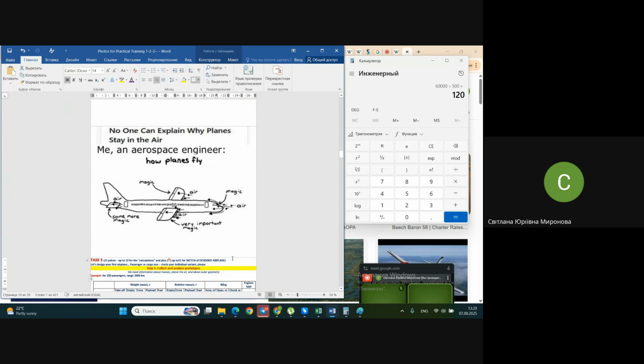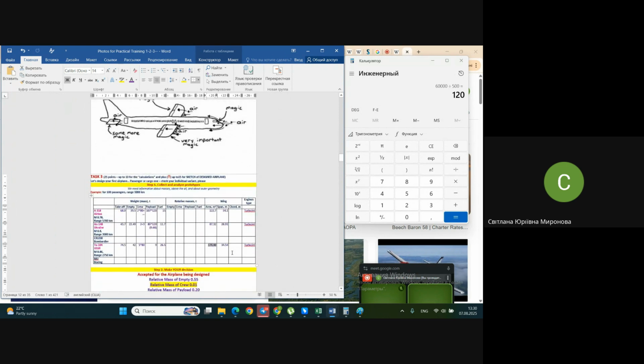First, to estimate a newly designed airplane, we need to collect statistical data, considering that we know only what our payload is and what the range is. Approximately, we may take information from our customer about what speed of flight they prefer, or maybe they don't know it. Maybe it will be your choice next. And we collect information about weight, geometry, and composition scheme of other airplanes of the same class, approximately for the same amount of passengers or payload, and approximately for the same range.